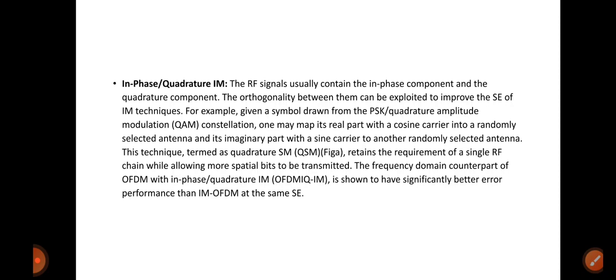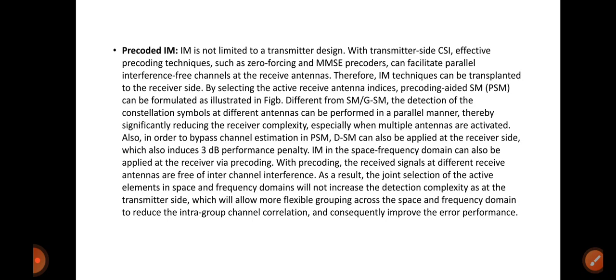Pre-coded IM. IM is not limited to transmitter design. With transmitter-side CSI, effective pre-coding techniques such as zero forcing and MMSE pre-coders facilitate parallel interference-free channels at the receive antennas. Therefore, IM techniques can be transplanted to the receiver side by selecting the active receive antenna indices.